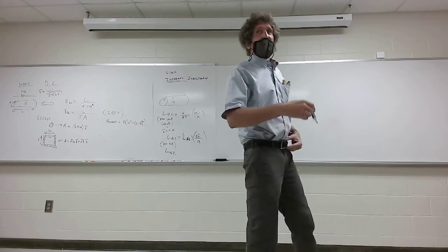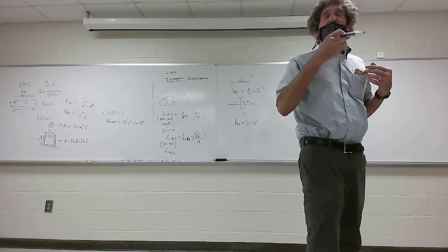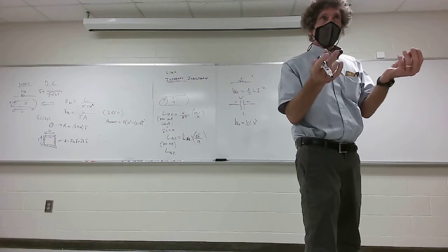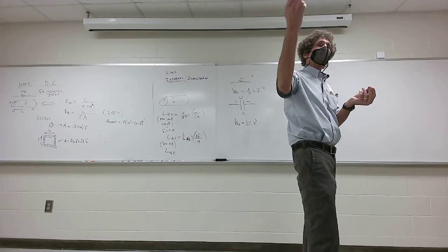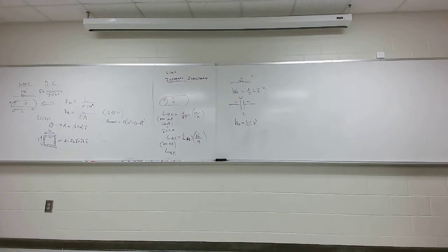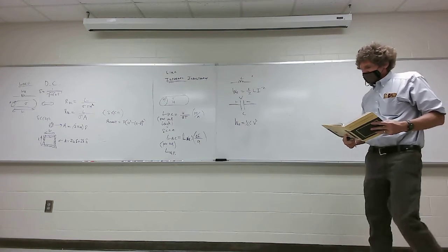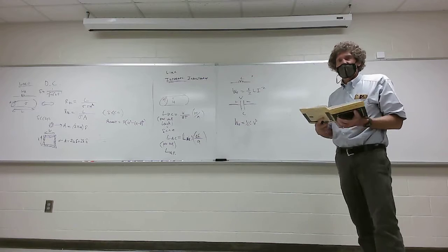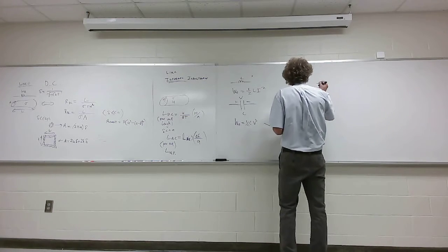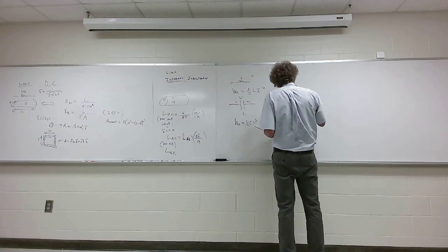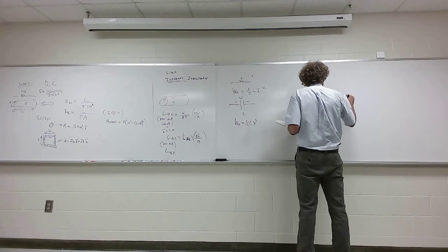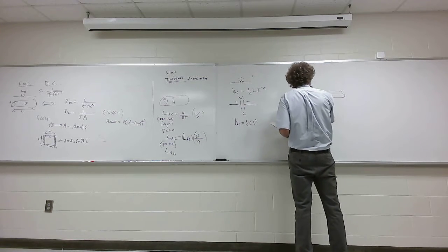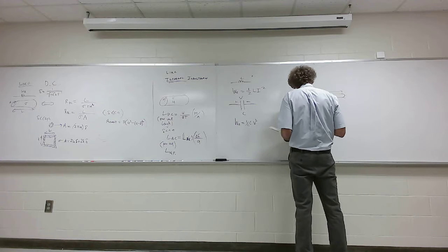Now, here's the deal with inductance outside the actual wire. When you have an external inductance and you just want to estimate, there's a lot of ways to do this. I will give you this formula if I expect you to use it. On page 505, he talks about the partial inductance formula. This is only one of many. So if you have a wire and you basically want to estimate without knowing the return path, this is L, the external inductance. This is L external.